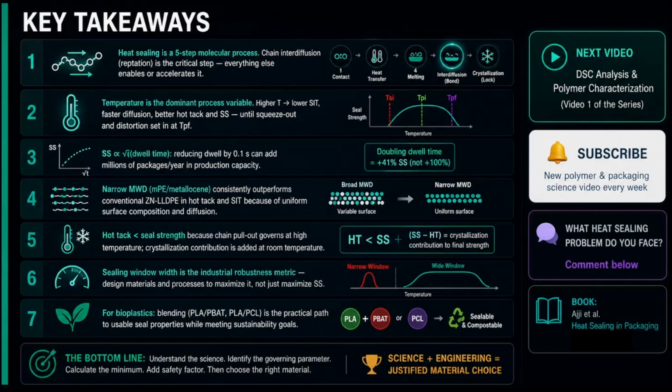6. The sealing window width is the industrial robustness metric. Wide windows, robust process; narrow windows, fragile process that fails when anything changes. Design materials and parameters to maximize window widths.